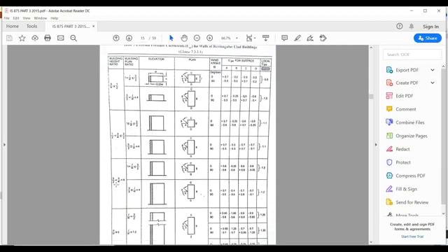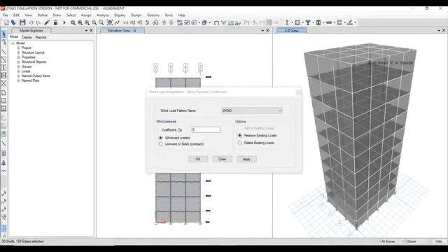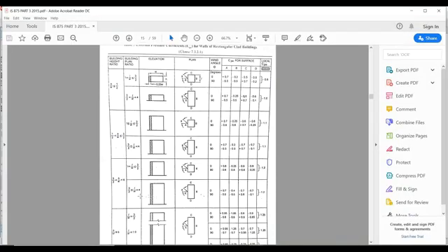which is between 3 by 2 to 6. And from 3 by 2 to 6, we will be having length by width ratio. So length is 4 spans of 4 meters, 16 meters. So 16 meters of length and width is 12. 16 by 12 is 1.33. 1.33 is between 1 and 1.5. So from this, at theta equal to 0 degrees, we will be having the coefficients of plus 0.8 in A direction and minus 0.25 and minus 0.8 and minus 0.8 in remaining directions.